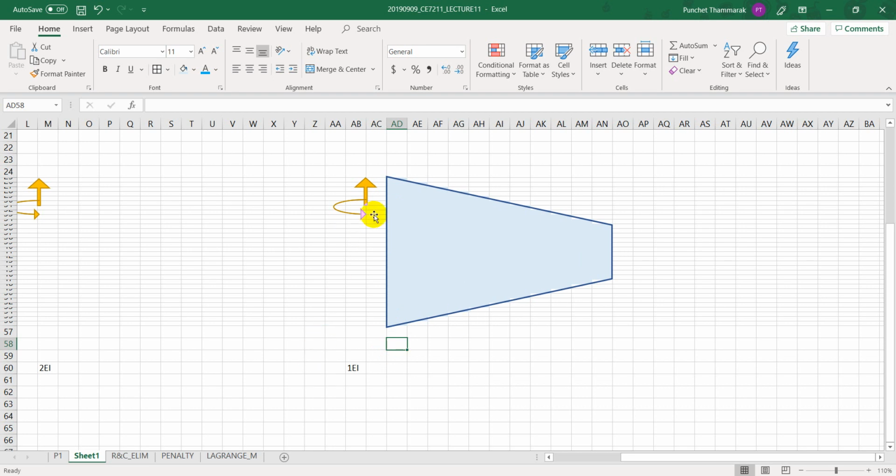Now you have one beam member, two beam member, 3, 4, 5, all the way to the 16. Out of these 16 beams, none of them have the same EI value because the EI keeps changing with the position. So you find the EI at the middle of this sub-beam and put it into your sub-beam.